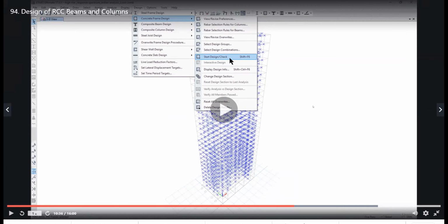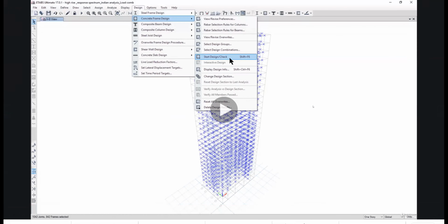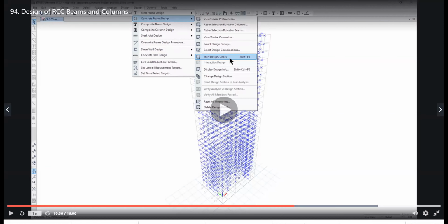So when we design these towers that are surrounding the city, those towers will be affected more due to, sorry, I told it in reverse. Actually, as the weight increases, the impact will be more. If the weight is less, then it is not effective. That is, base shear equals W into the coefficient. If the weight is more, then base shear will be more. I'll just show you one small example over here.